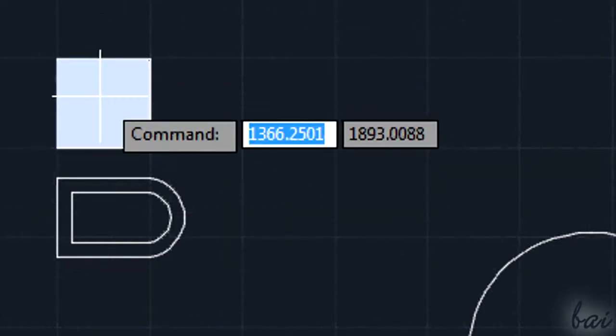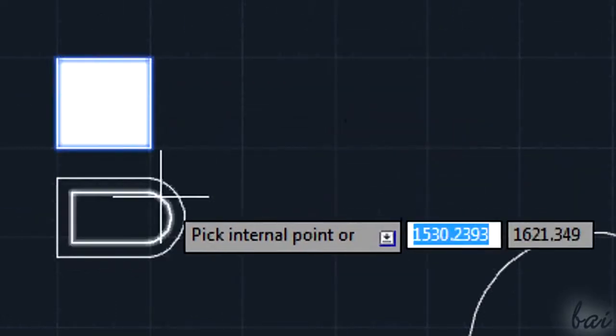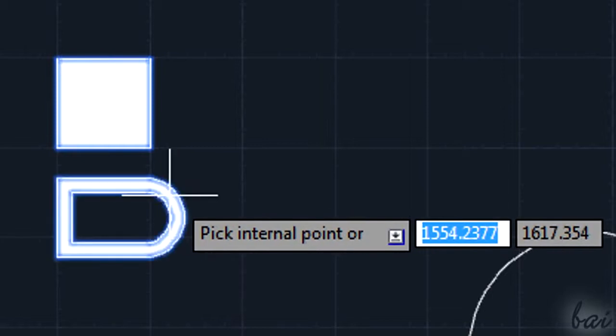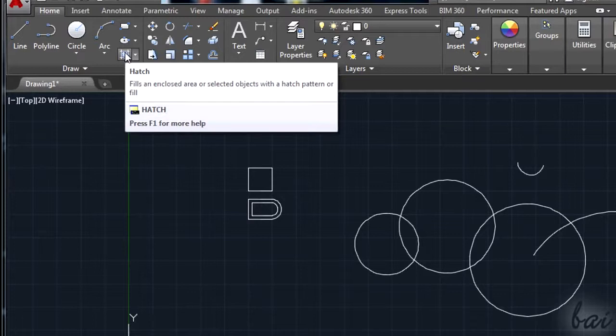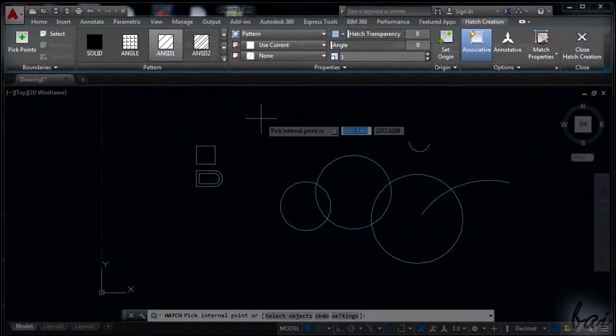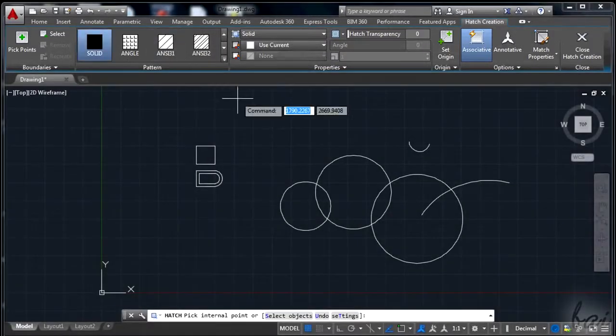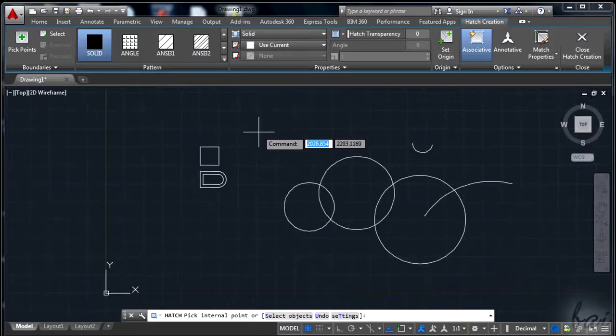What if you want to fill up this letter D? You can add filled areas using the Edge tool. This is located right below the Ellipse tool. A new window called Edge Creation appears, containing all you need to fill enclosed areas.